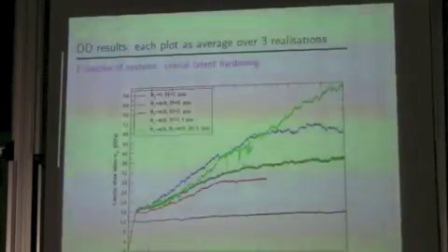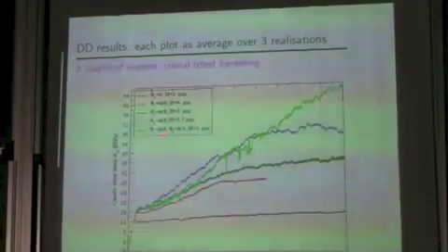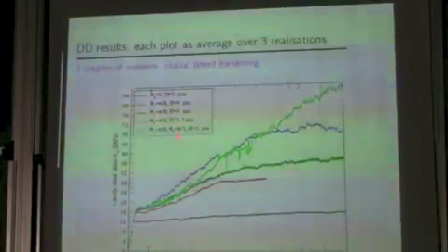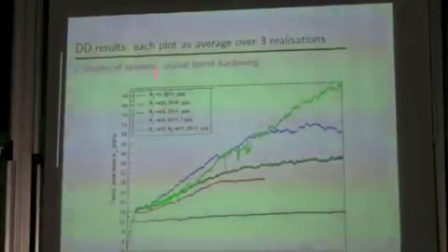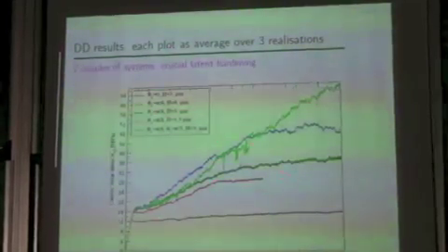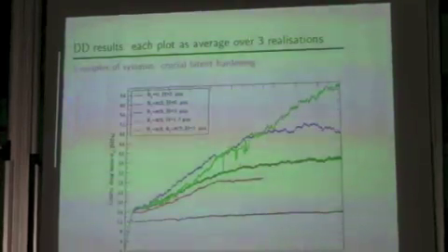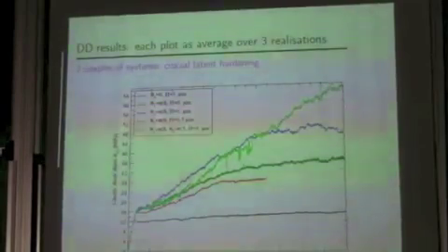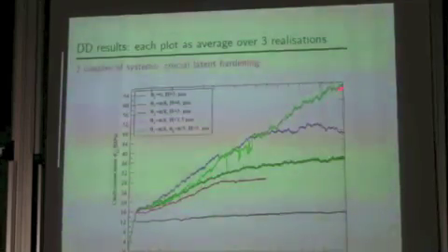And now, when you add a second couple of systems, inclined at pi/5, you see this huge latent hardening effect. So we give the sample one more possibility to glide, to develop plastic deformation, but in spite of this, the stress strain response is almost always stiffer.